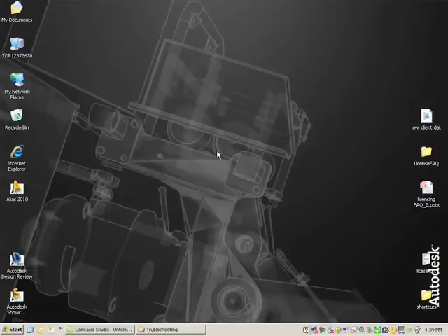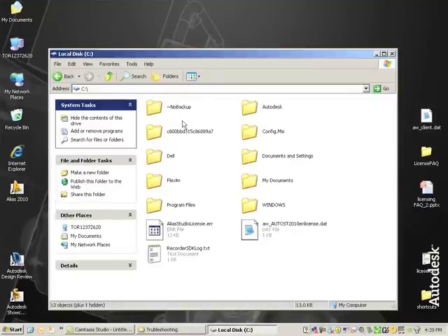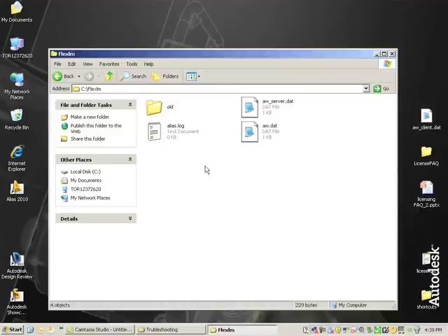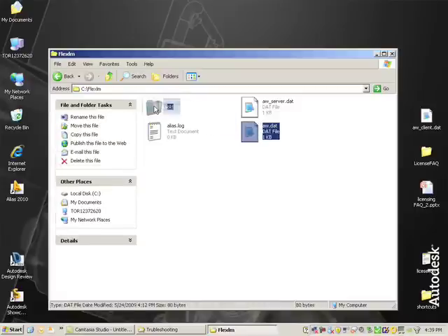The first place I would start, just like I did with NodeLock, is your license file. That's the first thing to check. So you go to C, FlexLM, and check the basics. See here I have a aw.dat file. This is my NodeLock license, which is okay to have. It is separate from my floating, but just for testing purposes I want to get rid of that.